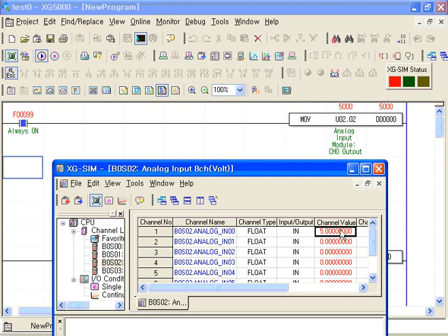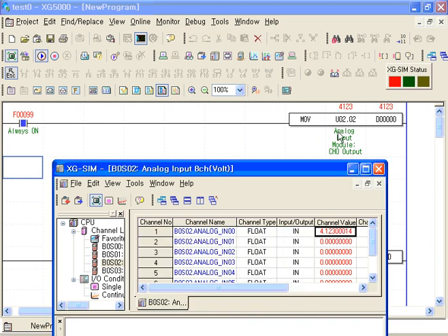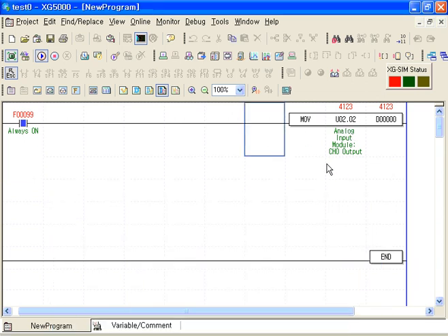So I change 4.1 to 3. Right? By this, this value. That's for analog input. Right? So let's say this is input, 5 volt is applied here. Then the value is 5,000, right? So this 5,000 digitalized value, I move it to some special address to make output, channel output to analog. Then 5 volt is made to the output.